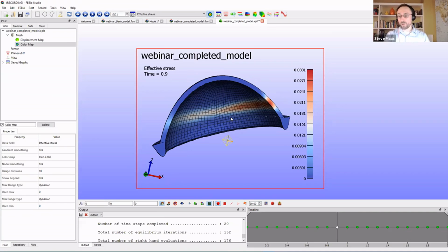software. But one of the problems you'll have if you do that, especially when you're dealing with big models, is that FEBio Studio cannot render this very fast. You can only get maybe 5 frames per second. So when you're using third-party software, you're just recapturing that very slow animation. What's happening here, on the other hand, is that every time it re-renders the screen, it grabs all these frames and puts them in the video, so that the video will always be a very nice and smooth animation.